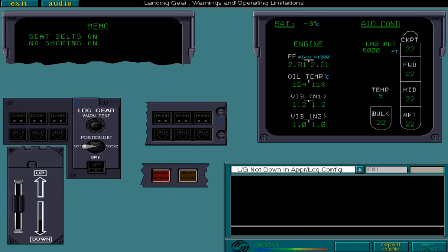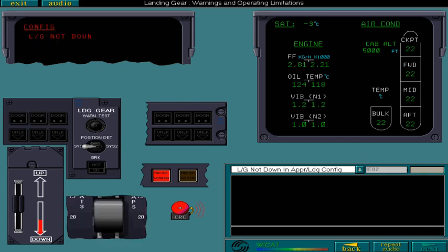We are now in approach. Select the forward icon to simulate a warning that may occur. Read the left ECAM messages and analyze the landing gear indicating units and local warnings. When you're ready, press the forward icon to continue.